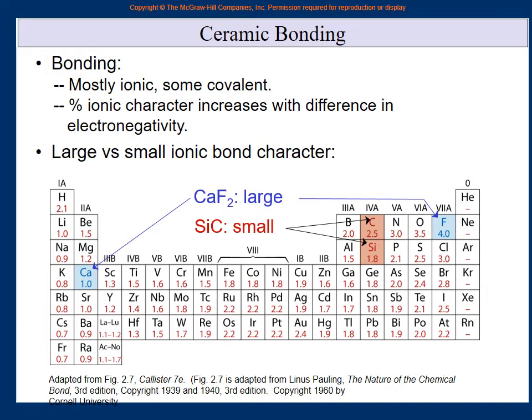But then how do you cut tool steels themselves? Tool steels are very hard steels. So you use tool steels to cut normal steels. But if I want to make the cutting tool itself, then what material should I use to cut this? This is already very hard. So silicon carbide is a ceramic. Its strength and hardness is much more than metals. We make only a small tip of silicon carbide and put it on a normal cutting tool. Now it is a normal cutting tool, but the tip is made of silicon carbide, and this is much harder than even tool steels, right? So silicon carbide is one of those materials used in cutting tools and so on.